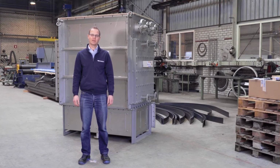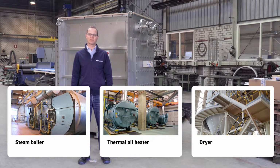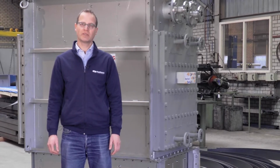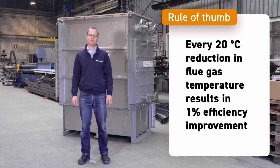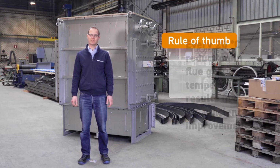Economizers are typically installed behind steam boilers, thermal oil heaters or drying processes. By waste heat recovery, you reduce your energy consumption, your CO2 emission and your cost in the end. As a rule of thumb, every 20 degrees Celsius reduction of your flue gas temperature around the steam boiler leads to 1% energy efficiency improvement.